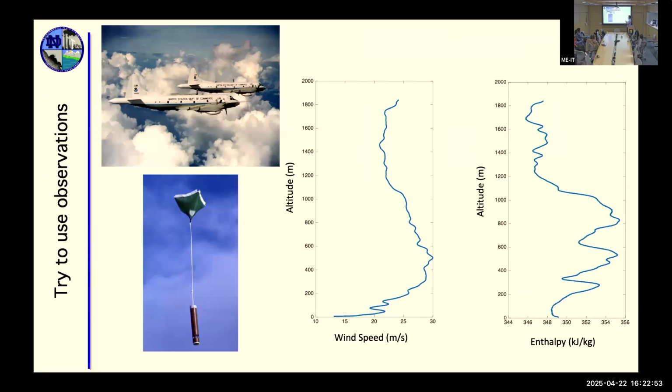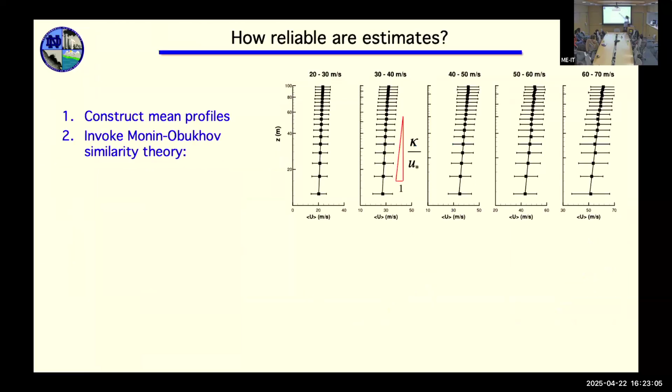And so what we did, just copying Powell, was we took the average boundary layer height in these hurricane boundary layers, which is about 500 meters. So we take 500 meters downwards and we just compute the average wind speed. That's a number. And then we say, does that fall into 20 to 30, 30 to 40? Which bin does that fall into? So you take all 20,000 of these SONs, you put them into the buckets, and then once you're done doing that, you average them all together.